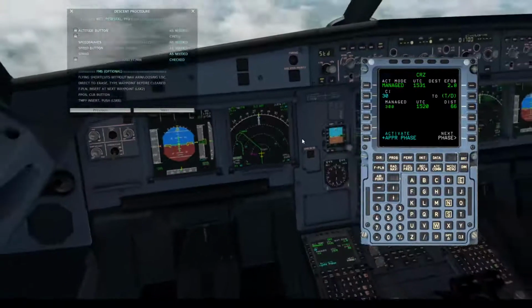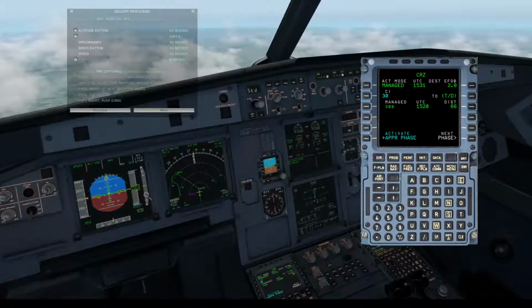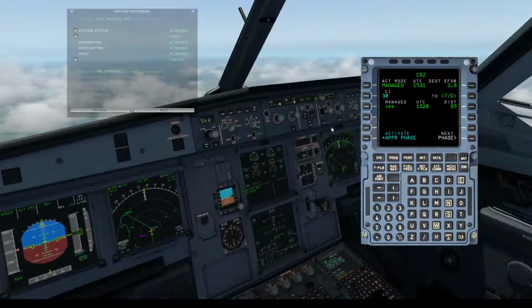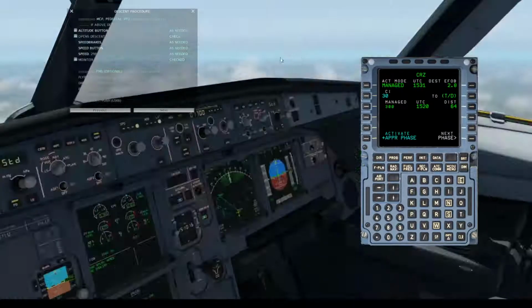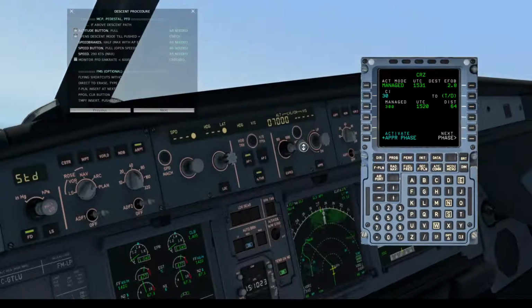And the reason for this is if you come into some strong turbulence now and the aircraft will sink a little bit, then it might not know which altitude to go back to. So normally just leave it at your cruise level until shortly before. Actually, let us do that just to be safe. Or we'll dial in something a bit closer.